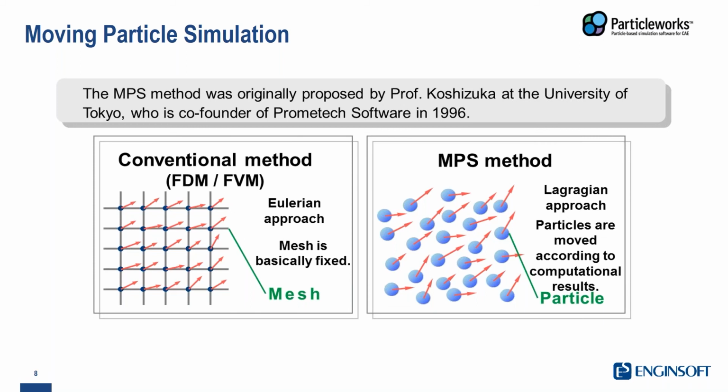All these problems that are typical of e-drives and transmission systems can be totally removed from the process using a Lagrangian approach. The Lagrangian approach basically means that you discretize the fluid by particles instead of cells, and you calculate the trajectory of every single particle, accounting for the interaction between the particles. So you account for the energy transfer and the momentum transfer, and you can solve the velocity, the pressure, the temperature, and turbulence of every single volume of fluid.